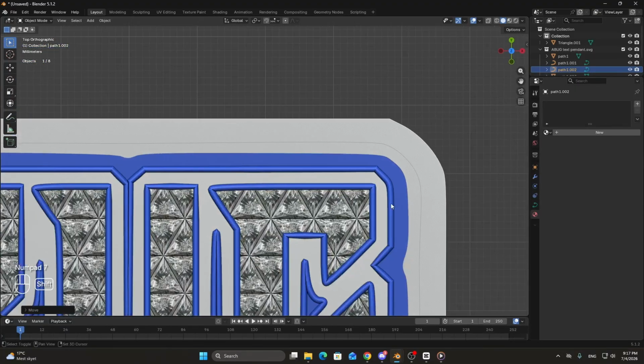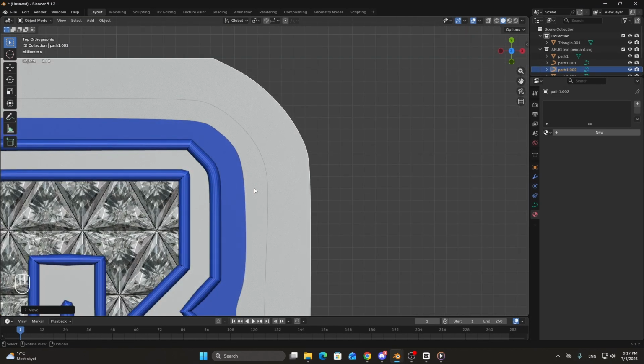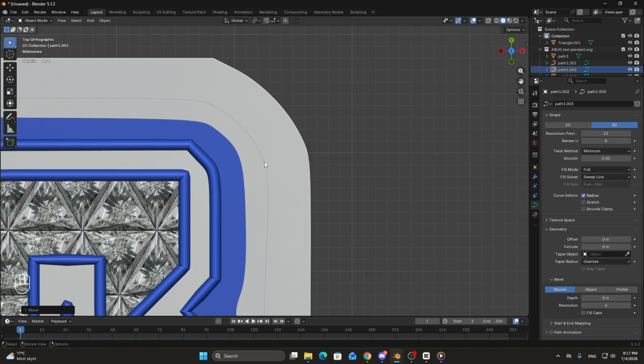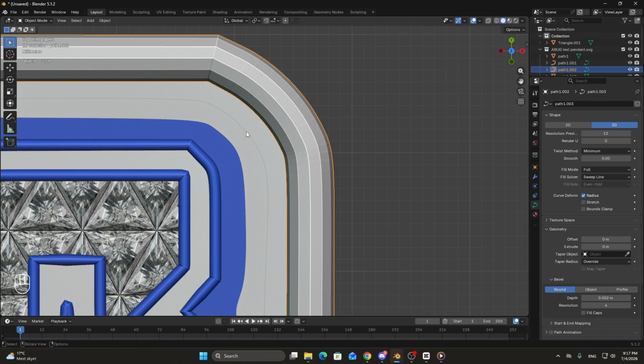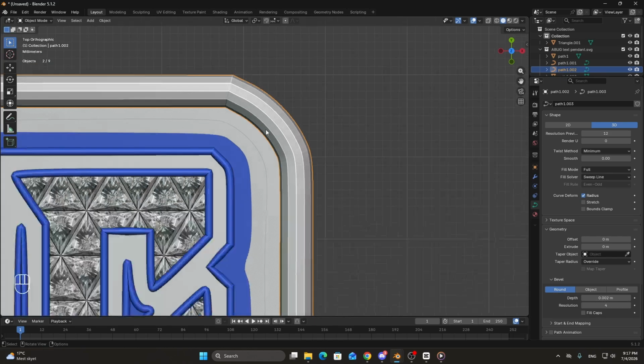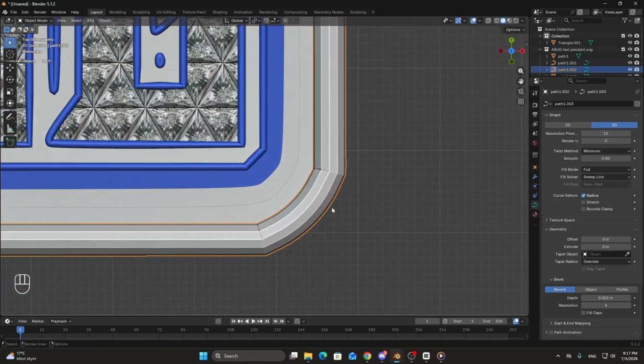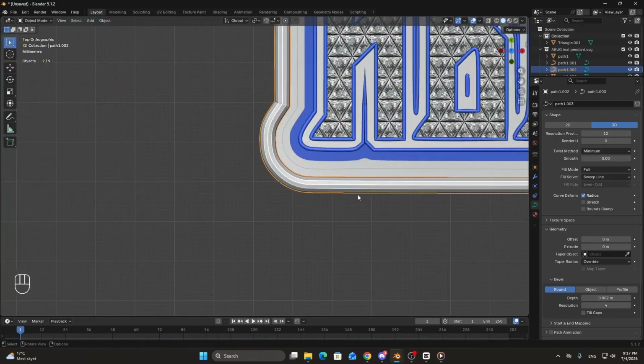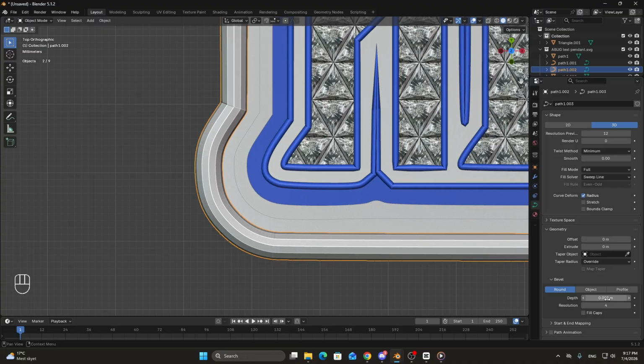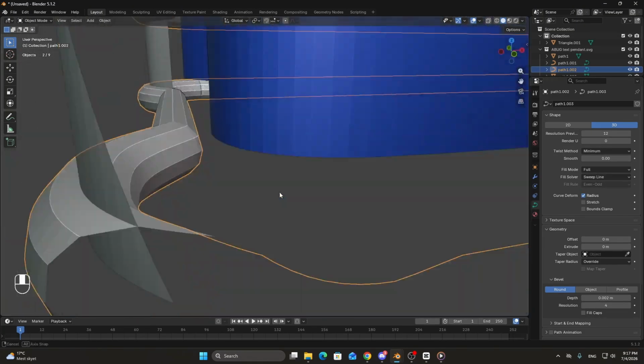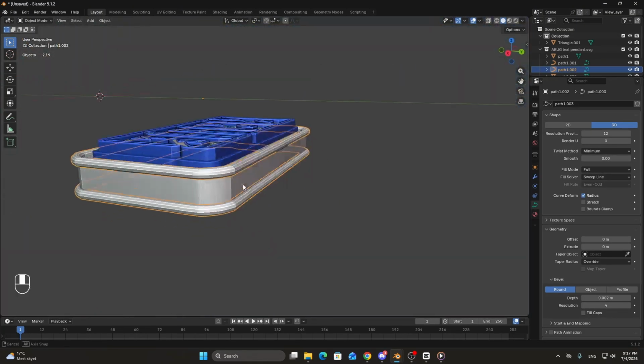Now go to the top view, press 7, go to the top view, go into data again. And you see this line, this is where the diamonds will be. So we're going to try to make the depth so it's just as much room here as here. And this looks honestly pretty good. So 0.002 for the depth.